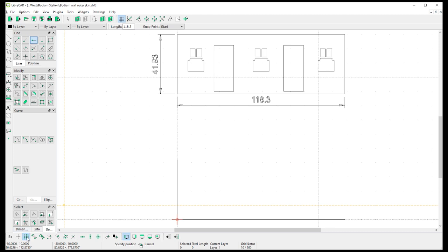I'm going to turn that grid lock off now, and if we have a look, we've got our vertical line, our end of our wall, and our baseline in. And we could repeat that process. I could put another horizontal line in and just attach it to the end. In fact, let's do that very quickly. Let's go to horizontal line tool again. If I were to choose this tool here, this will snap on an end point. So I can select that tool, and it will now want to snap to either end of those lines.